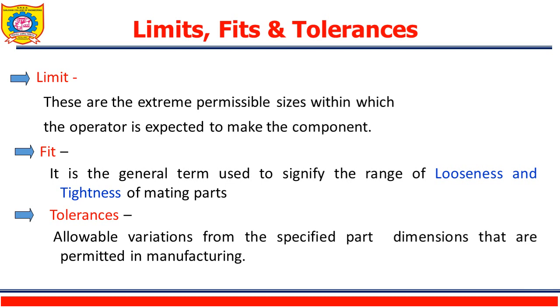Fit. So what is the fit? It is the general term used to signify the range of looseness and tightness of mating parts. We know that the manufactured components are going to be assembled in order to form an assembly or a system. So whenever we manufacture and assemble the different components, the degree of looseness or tightness of these mating parts is nothing but the fit between those mating components.